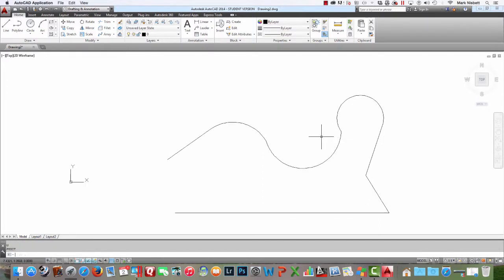And I want to go back into Polyline Edit again. The next option is Edit Vertex, and then we have Split, Spline, Decurve. We've seen line type generation, and then there's Reverse and Undo. This is where things can get a little bit complicated. If I type in E for Edit Vertex, the first thing that happens is I get an X right here. And notice that my options change down bottom. We have next, previous, break, insert, move, regen, straighten, tangent, width, and exit.